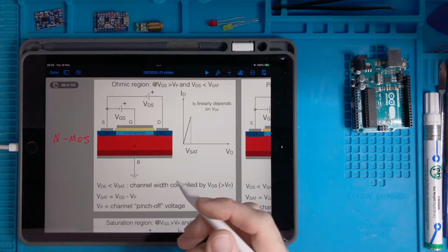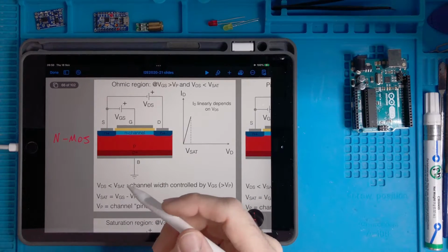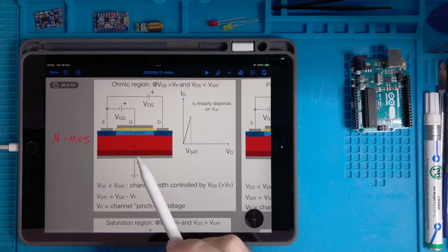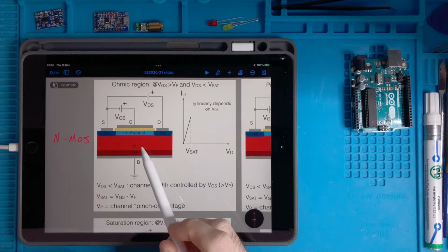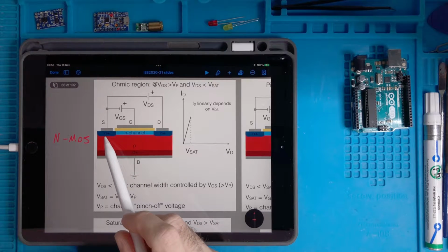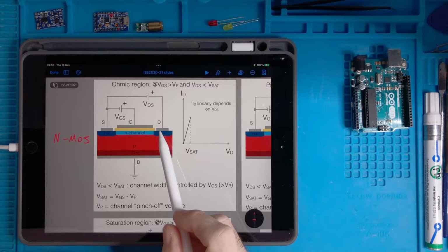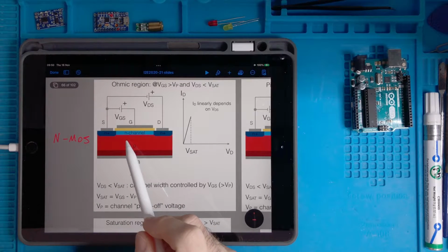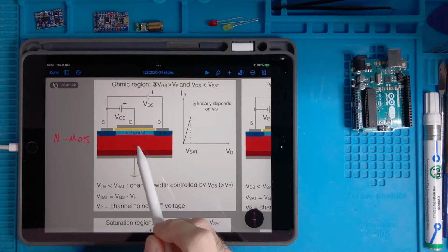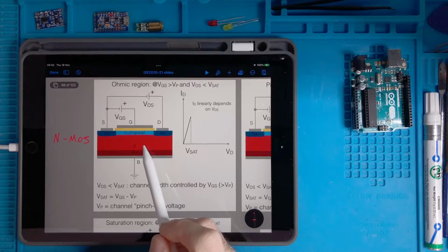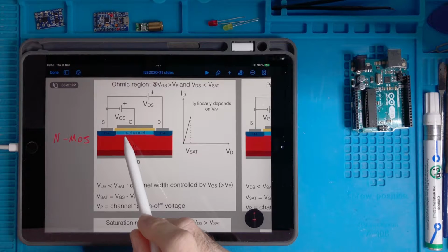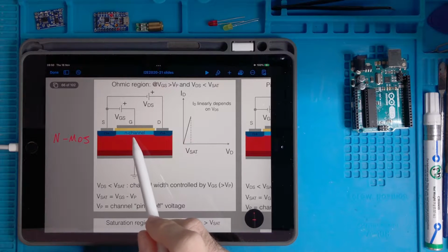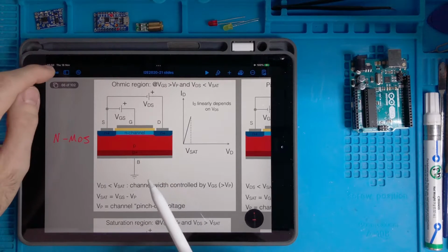So vice versa, we can manufacture a MOSFET in a complementary way. We put an N-type bulk material, then here we will have P plus wells for the ohmic contacts, and then correspondingly with the N-type material we will have a P channel, so a channel where the carriers of charge are not the electrons but are the holes.